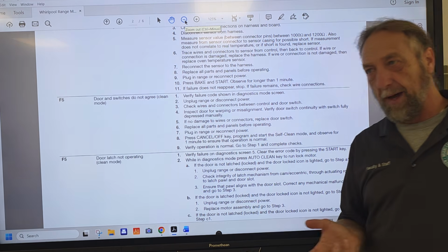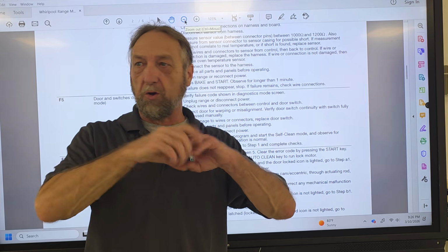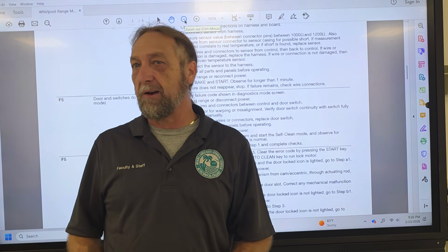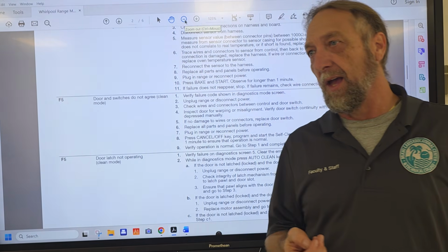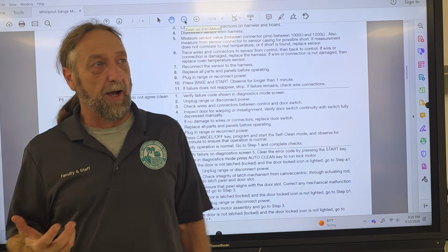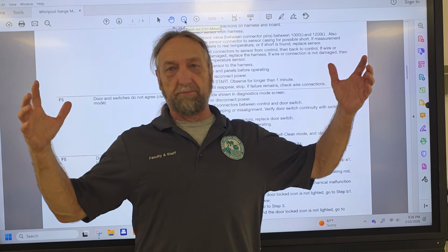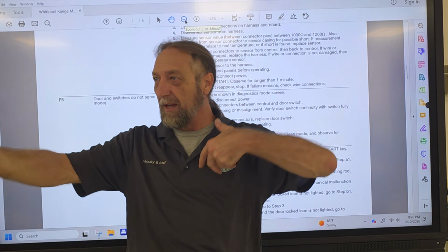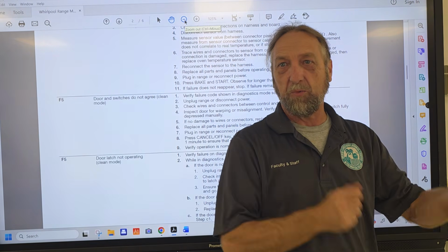Listen, wires don't go bad that often, even on ovens, okay? Usually it goes bad because the crimp, or the way they connect the connector on the wire, wasn't done very well from the factory, and it runs hot every time you use the oven. Now you got some people that cook 3 or 4 times a day. Down here in Hialeah, we have a lot of food trucks. We call them roach coaches, right? I've gone to people's houses and they've got a pot this big on a burner this big, cooking rice and beans and all these other things, and they're selling it to the guys driving the lunch trucks.